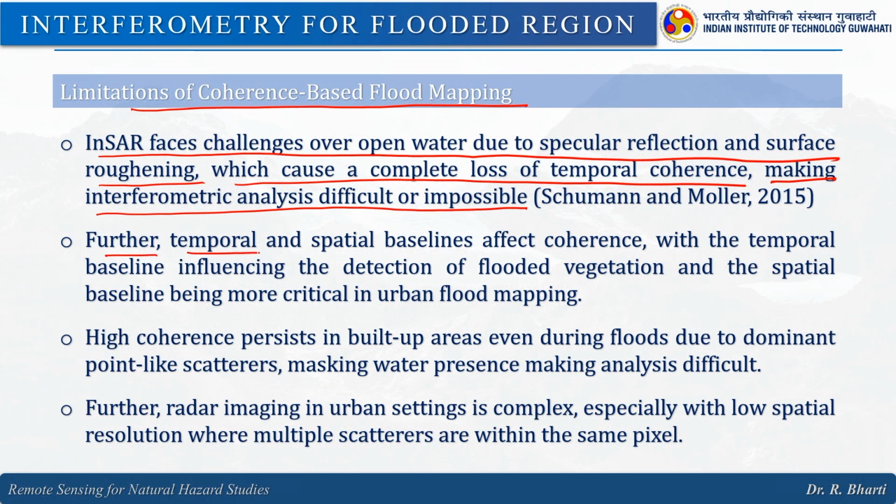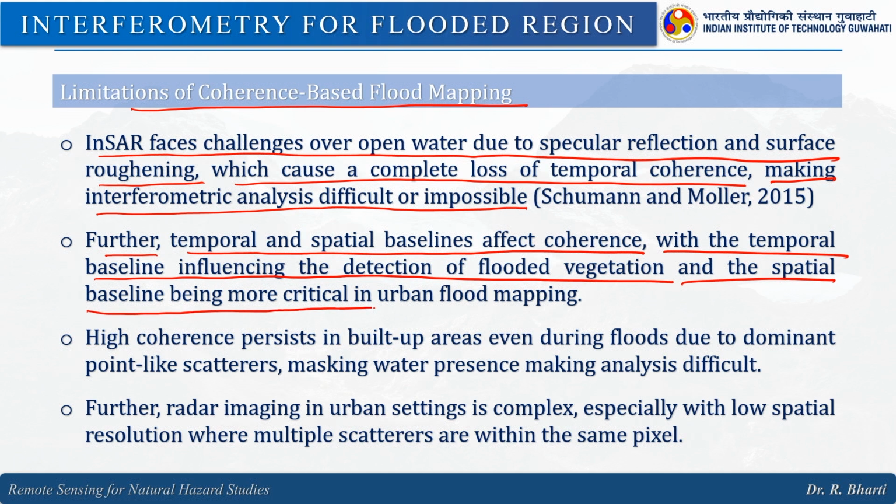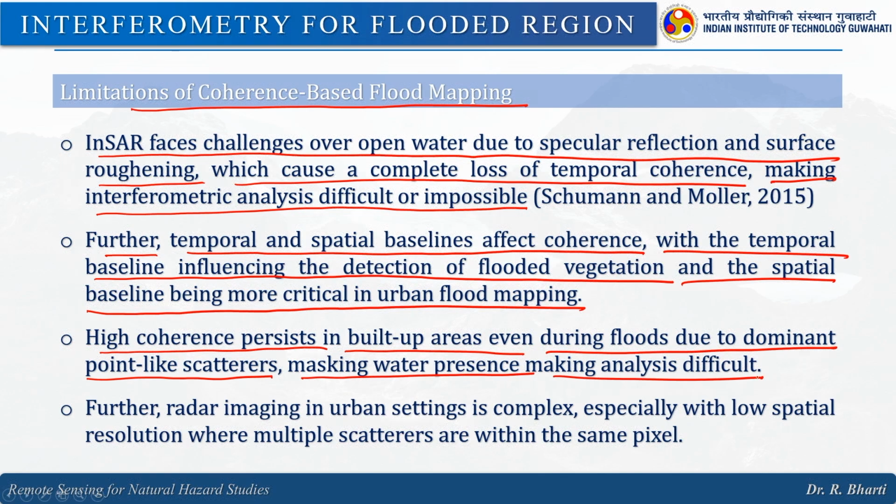Further, temporal and spatial baseline affect coherence, with the temporal baseline influencing the detection of flooded vegetation and the spatial baseline being more critical in urban flood mapping. High coherence persists in built up areas even during flood due to dominant point like scatterers, masking water presence, making analysis difficult.